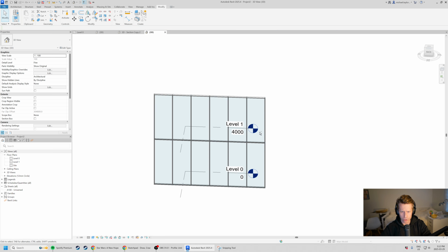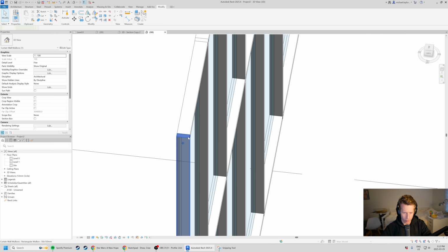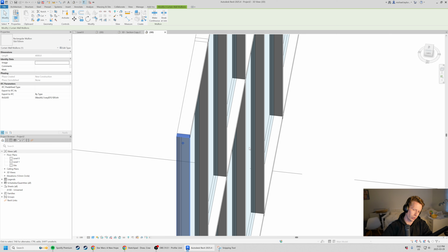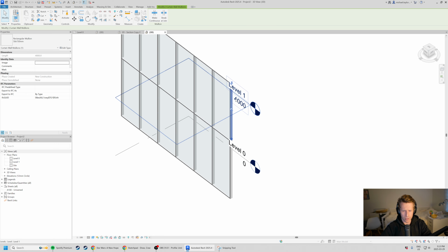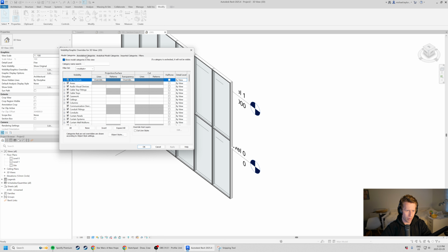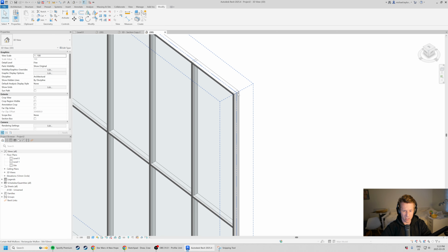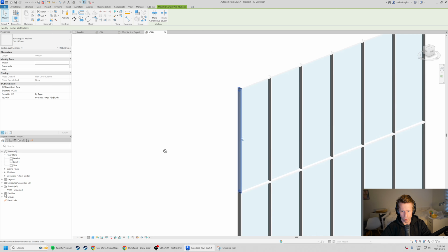So, blam, part 2. One thing I still see on projects from this semester, last semester, every semester in my time in the office, is people, for whatever reason, really like the idea of having these mullions on the outside of the building. When I say outside, I mean outside the enclosure. This is a support for your glass, a support for the glazing that's going to go on your building. So when we're thinking about what's happening in real life, what we want to see is those mullions on the inside. They're the support for our building.